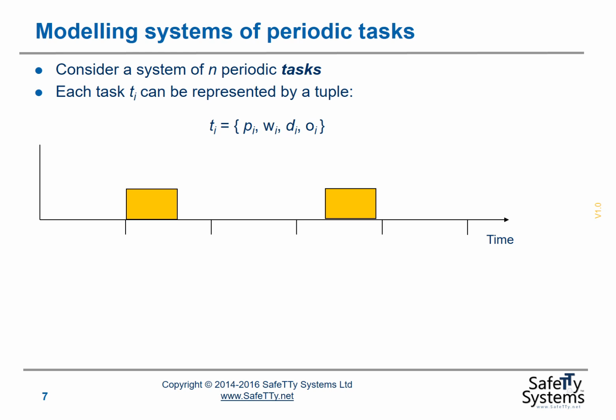So this is one example. That might represent our task period, in this case 2 ticks. Our offset in this case is 1 tick. So if the scheduling activity starts at T0, then we have an offset of 1 tick and we're releasing our task in the second tick.